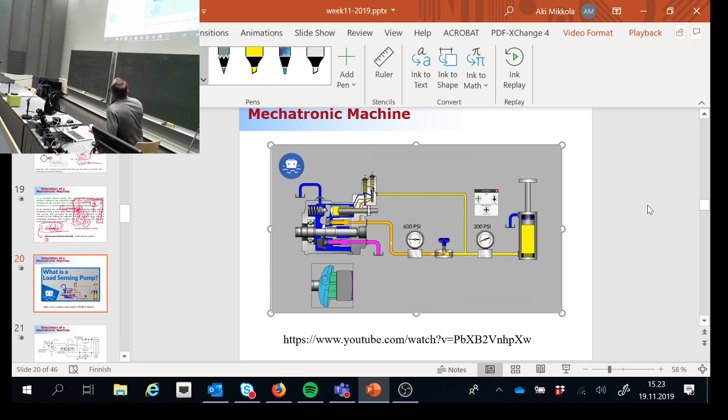How did I figure that out? I figured that out because our pump outlet pressure is set at 600. So it's taking 300 from the load and adding it to the 300 spring setting, and those two forces add together to give us our regulated pump outlet pressure of 600 psi. This is different from a pressure compensated pump, which might be set at, say, 2000 psi at all times, and therefore using a lot more input energy.